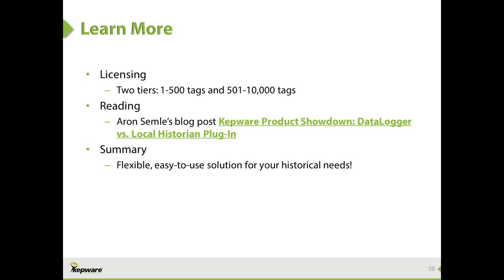So I have a couple questions. One good question up here: is the historian plugin part of the server_runtime.exe? It is dependent on that executable, so if the server_runtime is started, the historian plugin will be started. There's actually another service that you'll see in your services list also associated with the historian plugin that handles some other attributes of that plugin and how it functions. So it is dependent on server_runtime.exe to run.